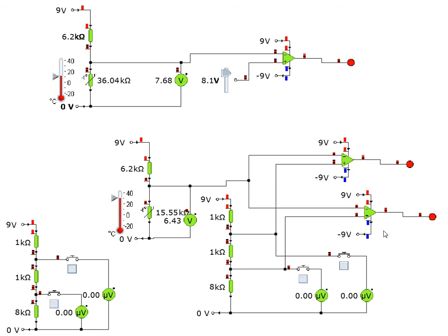There's nothing to stop you just having two comparators and 3 resistors. If you've got a fourth resistor, you can get a third comparator. It can be more complex than this, but they're all just building on the single comparator circuit. You can just think of them as related comparator circuits.